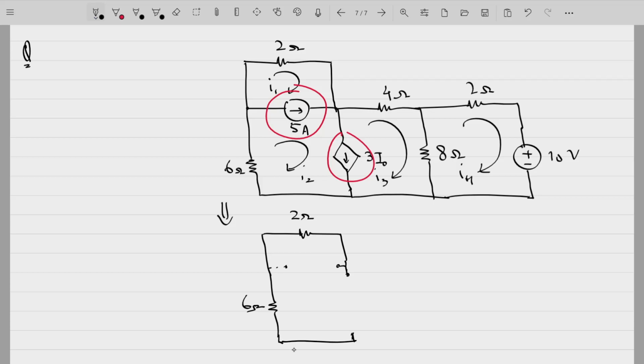Also note that I naught is this current. This is also open here. So this is 4 ohm resistance, 8 ohm resistance. So you have to only open the current source branch and all resistances in series with that current source.